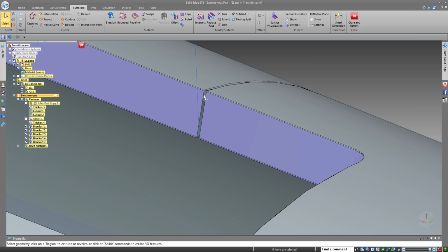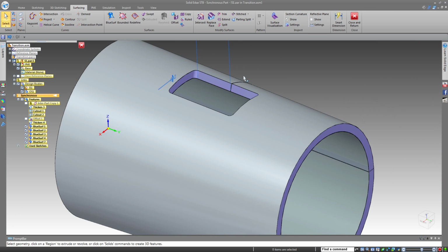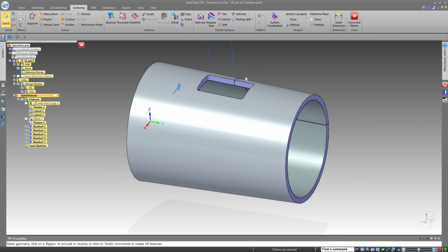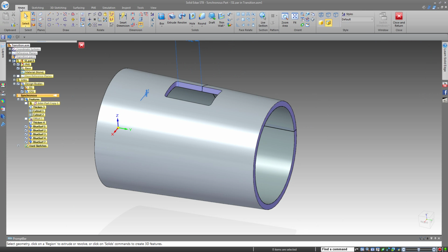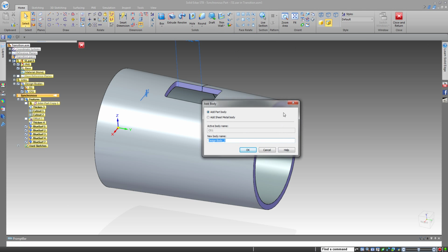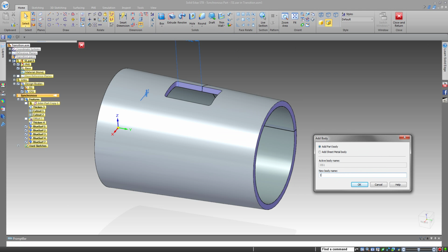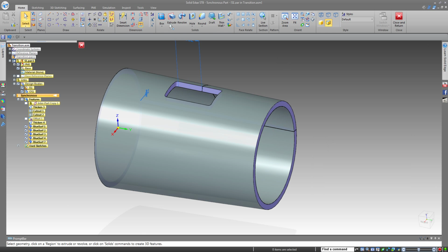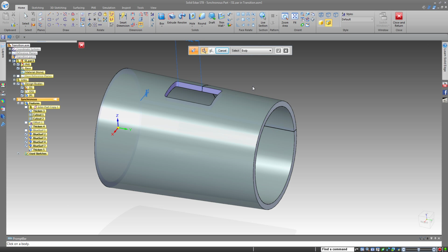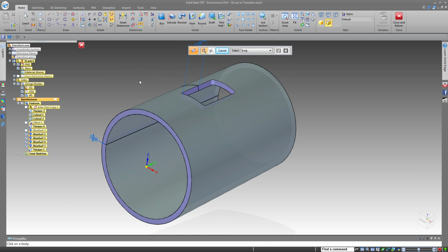So there's obviously a few other pieces like the inside piece here and there, but let's go ahead and start doing what we need to do to make this a solid body, which is to thicken these. All right, so now comes the step again. We'll say add body. We'll call this intermediate piece 1. It doesn't matter which one we start at, we'll just start down here and thicken that inside, outside. I guess inside would be beneficial in this scenario. Sounds good.